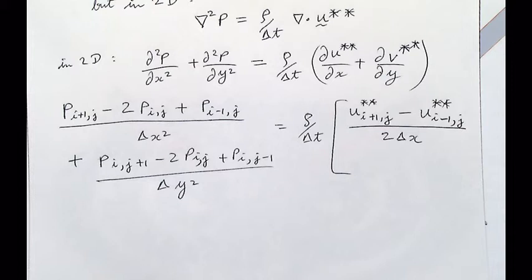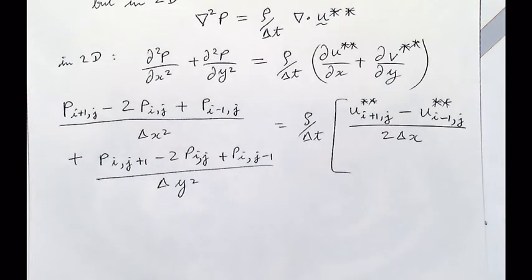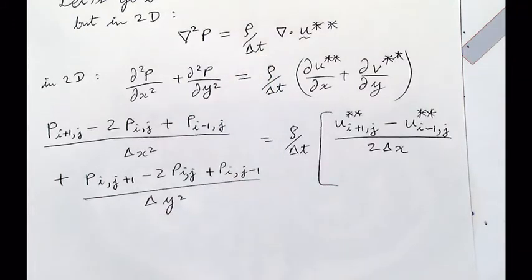So the question is, should there be a time component? Should we have superscripts where we have n and n plus 1? Thank you, I should have pointed that out. So what's the answer? No. This is not a steady state solution. We're solving the Navier-Stokes equation, the momentum equation, right? So there is a delta t over here. That's exactly what he pointed out. There's a delta t, but where are the n's and n plus 1's? Is this why we call it pseudo pressure? No, not really, but that's a very valid question. Why are there no n's and n plus 1's?